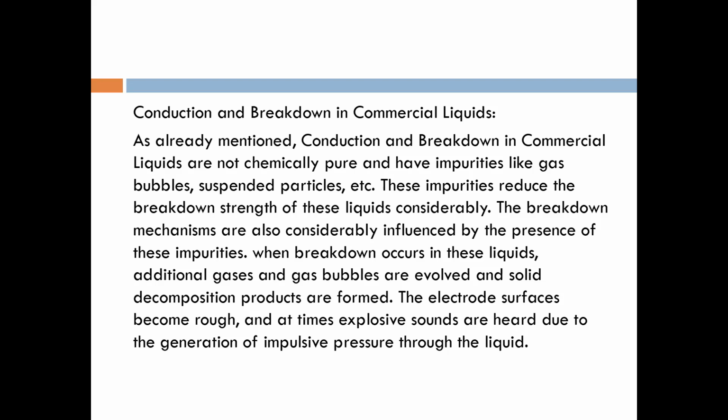Due to these impurities, additional gases and gas bubbles are involved, and solid decomposition products are formed. The electrode surface becomes rough, and at times explosive sounds are heard due to the generation of impulsive pressure through the liquid. It means these are the causes of breakdown in commercial liquid, mainly the gas bubbles and the suspended particles.